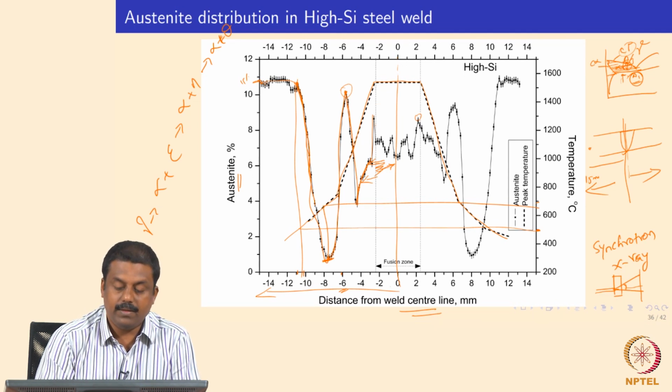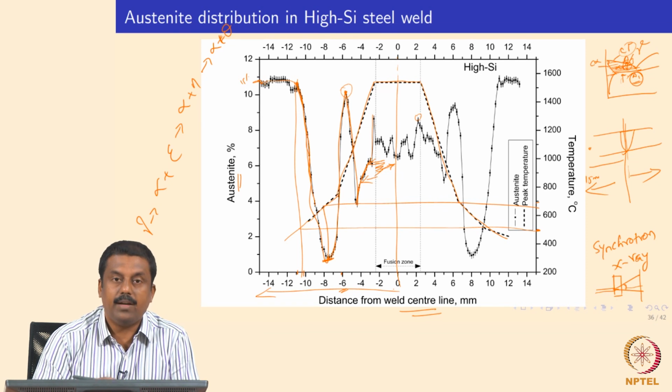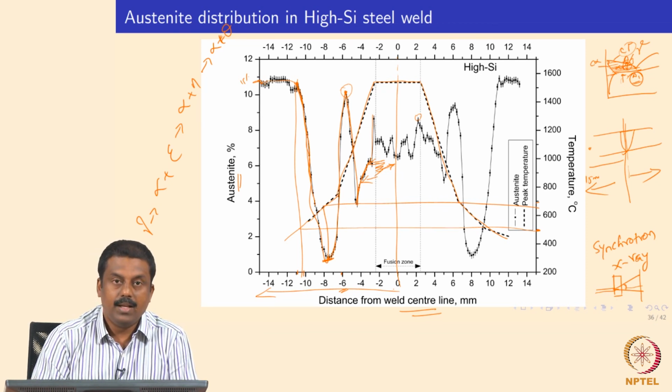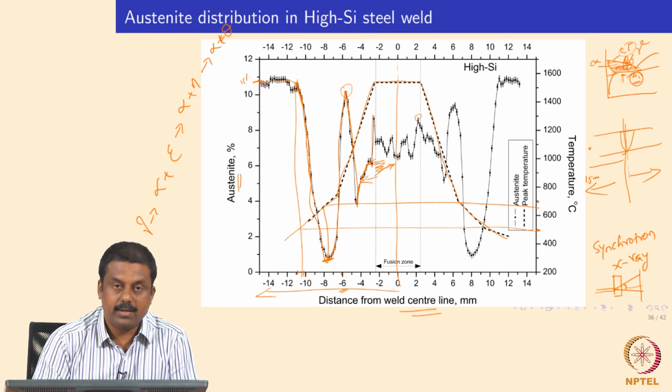So remember the definition of the heat affected zone. When you can measure the effect of peak temperature in the microstructure, and any noticeable effect is seen, then that is the heat affected zone.